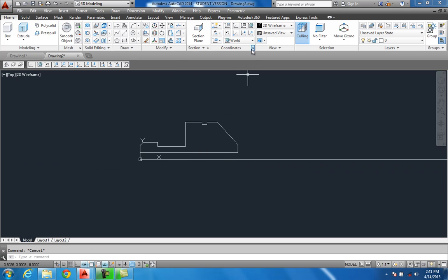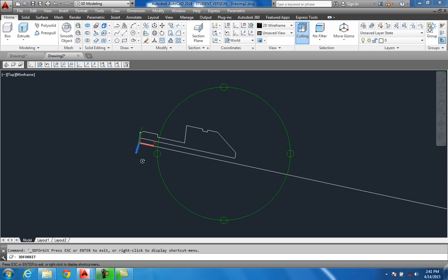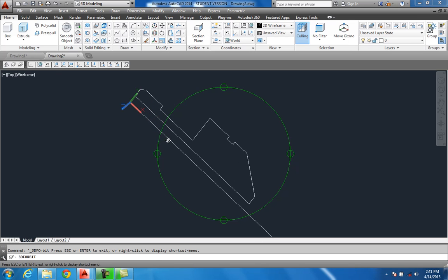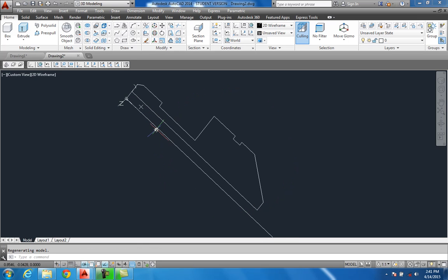And I want to spin this around, so hit orbit. I want to take a look at it. And again, whenever you're doing something symmetrical, you always go off the axis line and take half of it for what's going to be on the other side. So this hole in the bore is going to be a 1/2 inch bore. However, we only offset it 1/4 of an inch because it's going to revolve to the other side as well. And for your diameters, you take half, so it'd be your radius. From the center of this out would be your radius.